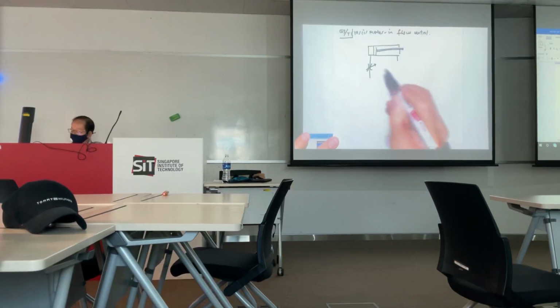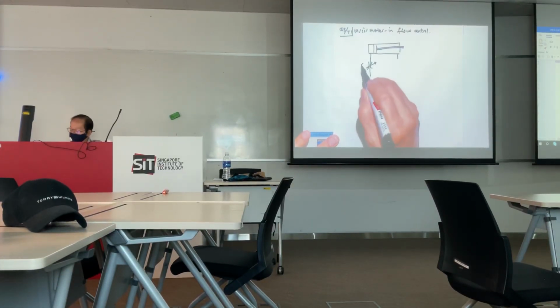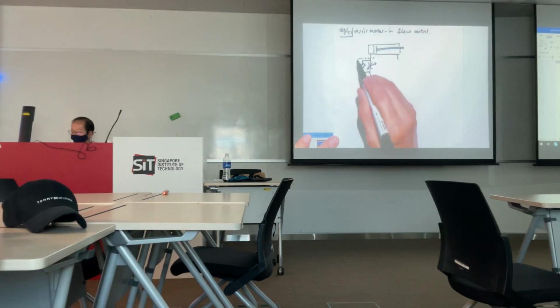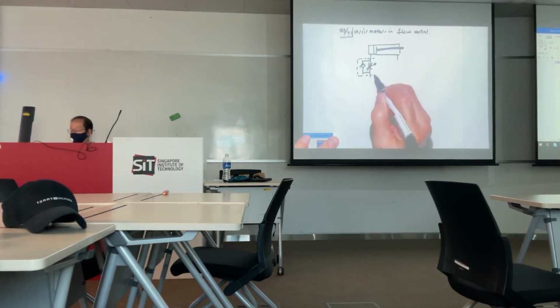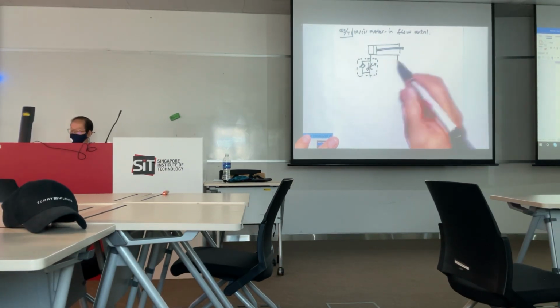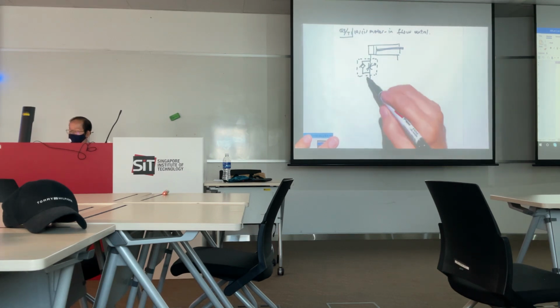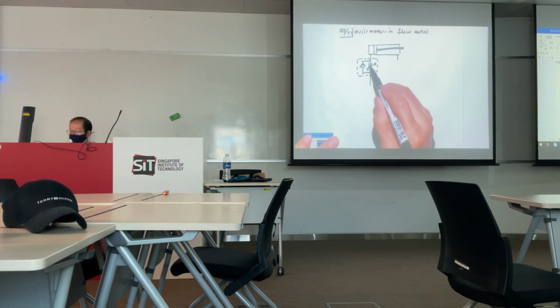So this is your throttle valve and your check valve. The V is an inverted V, and this is sealed as one unit. The fluid going in will have to pass through this throttle valve, which has an adjustable orifice.